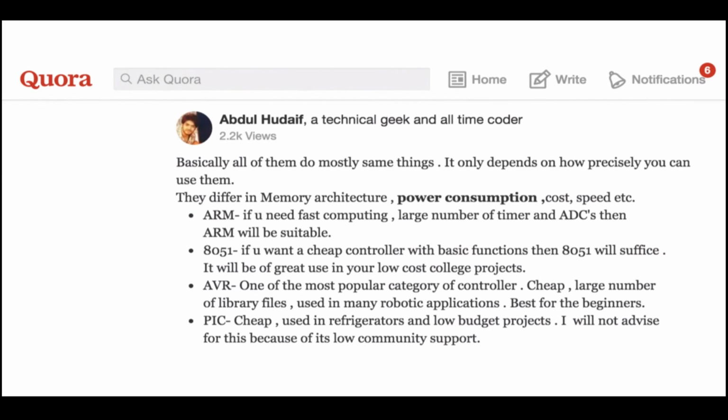And 8051 is not as sophisticated as the other two. One example is the Nordic RF module I showed you in the previous slides. That uses 8051. I remember reading it in the user guide. It uses an 8051 based microcontroller within itself to manage the queues, and when it has to interface through USB to the laptop, it uses the 8051 based microcontroller architecture to define the queues and implement that part.